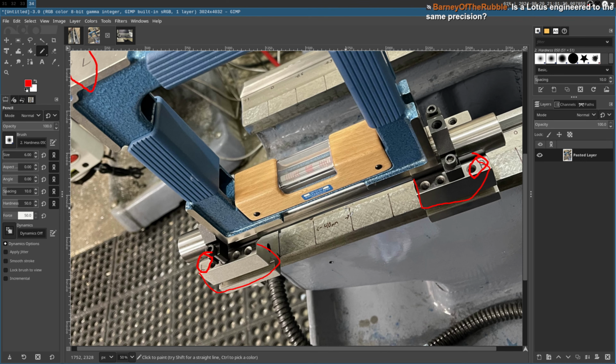So since we are only bearing on these feet at this distance, we're actually measuring more accurately than that 50 micron. Let's say the actual body of the level is 20 centimeters. If you were to just set that level on something, since this is measuring a ratio, your denominator here is not a meter. It is a fifth of a meter, 20 centimeters. And thus, you can just take that number, divide it by 5, and it's about 10 micron.